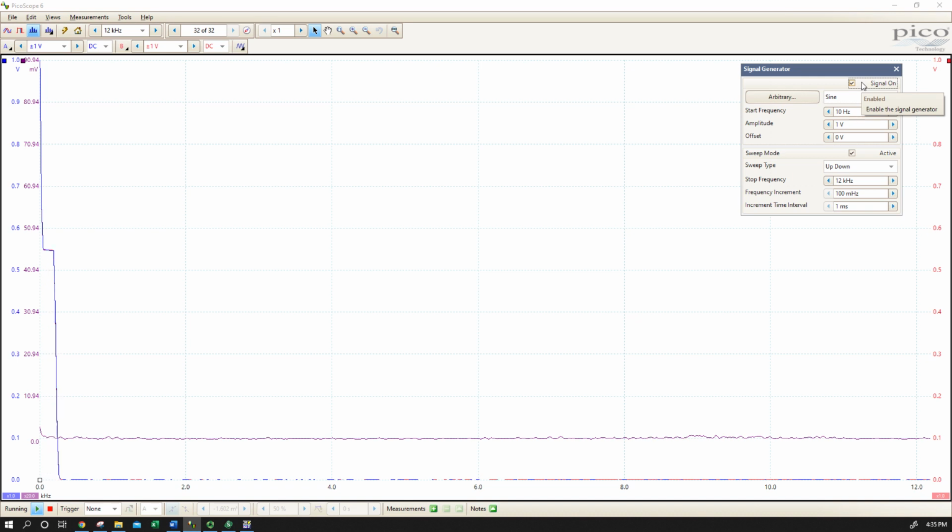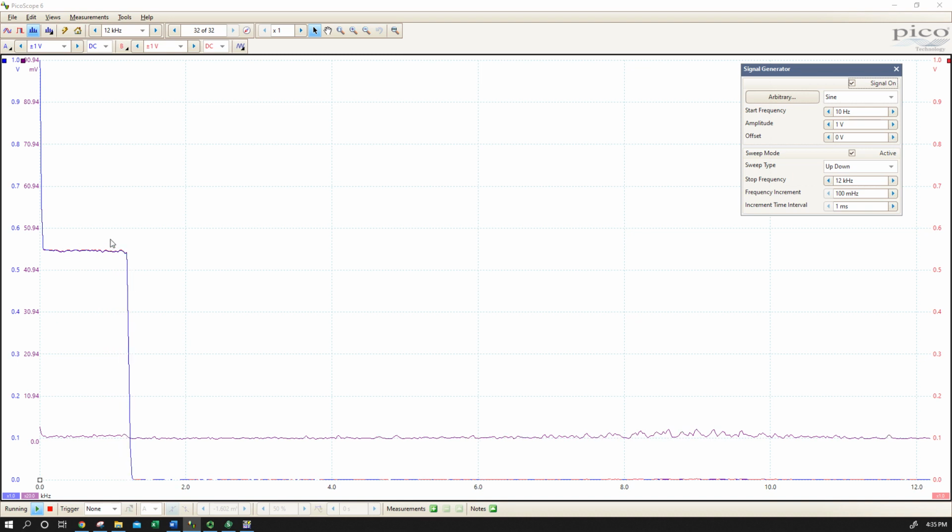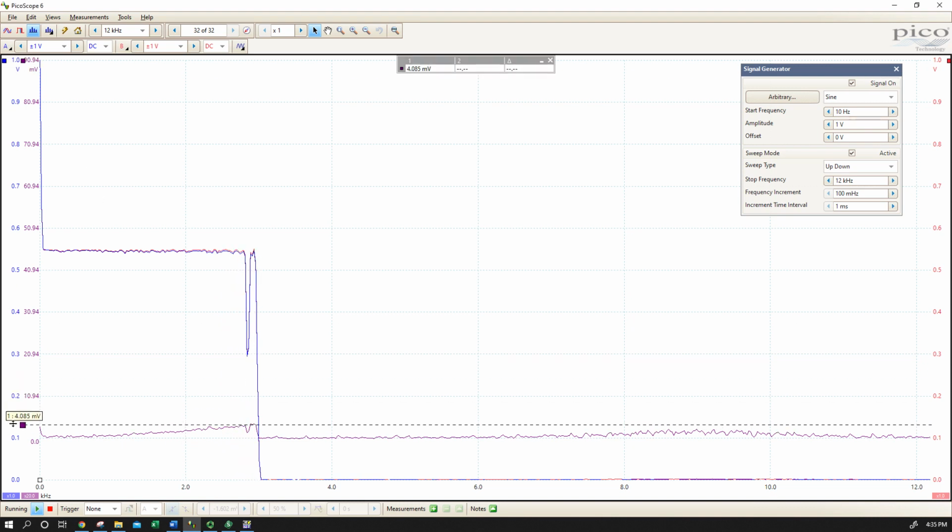So now we're going to start sweeping, and we can see we've got a fairly flat plot. So both the total circuit voltage and the load resistor voltage are pretty much the same. So for these frequencies, we're approaching 2 kilohertz. The inductor is not dropping a lot. But on our magnified scale, the purple line, we can see we went from 0. Now we're beginning to get a little bit, and we can track that. We had a little noise as we moved the slider there. So 4 millivolts, not a whole lot. We're beginning to see a little bit of separation.